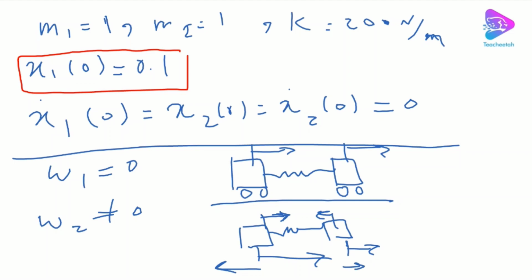So there is a sort of relative motion in between when we have the second mode. However, overall, the system response is the summation of them, which means that the system may move together while there is a relative motion in between. Say, for example, the two masses going one way, and at the same time they have a different displacement with respect to each other. So this is how we can imagine a semi-definite system motion, and why we have a natural frequency of 0, right? For the natural frequency of 0, it's more like moving together like a rigid system. There is no sort of vibration.